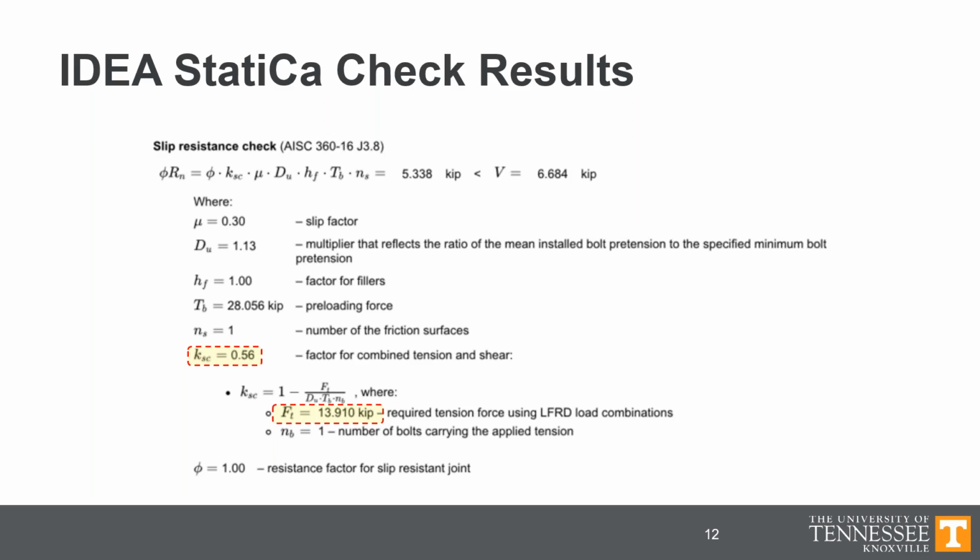is different than what was calculated in the example. And it's also clear what the reason for that difference is. It's the required tension force that goes into that equation that is different between IDEA StatiCa and what we see in the design example. While you can follow the calculations in the design example and they make sense to determine this T, the required tension force in the calculation, this value in IDEA StatiCa comes from the analysis, so there's really no calculations to review.